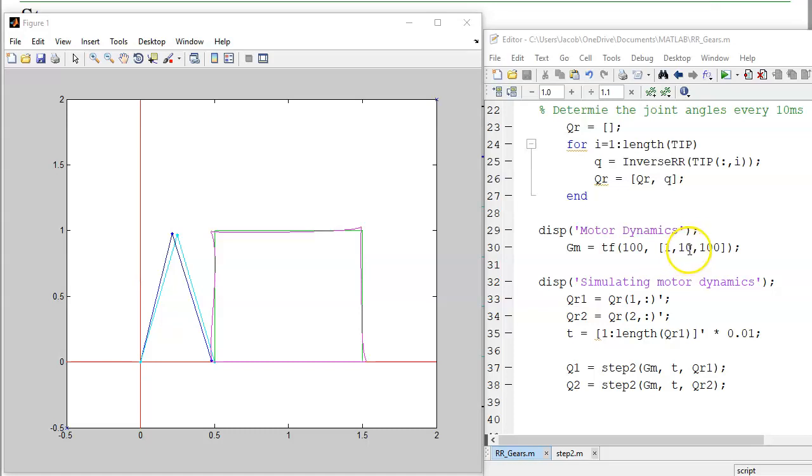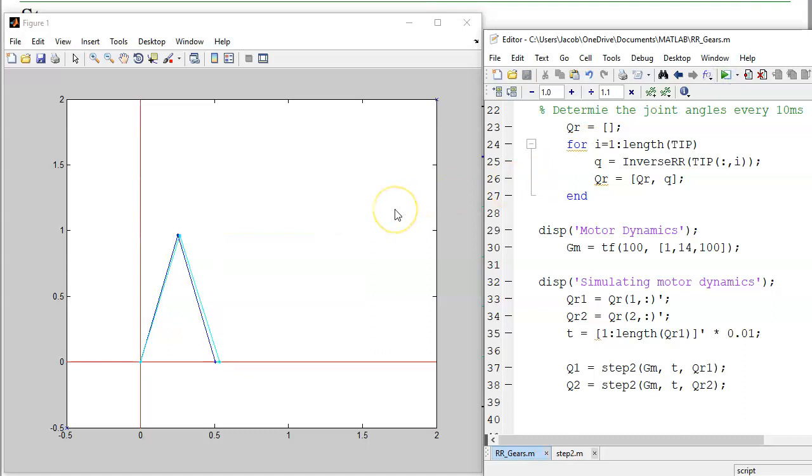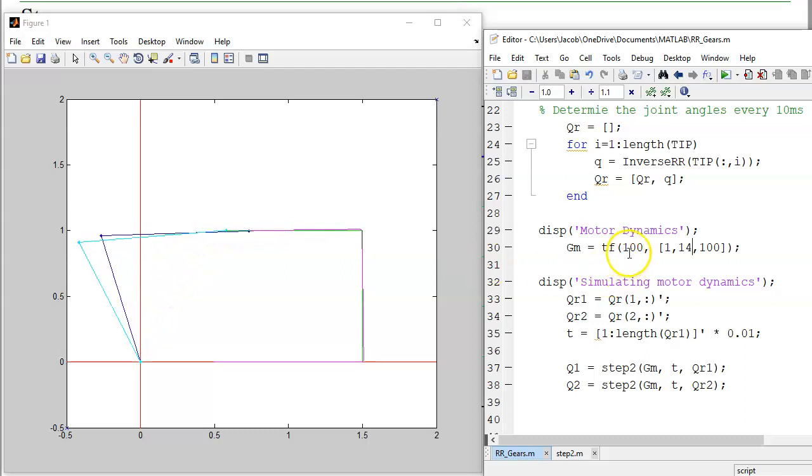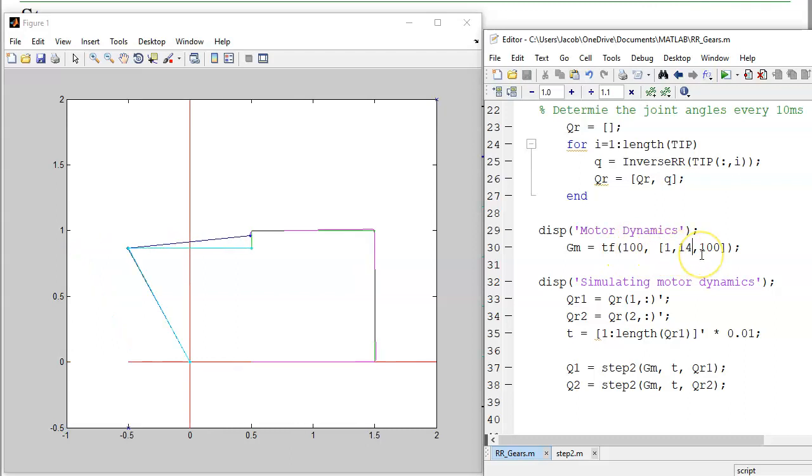In terms of the simulation, that'd be just changing this middle term right here with PD feedback. If I take this, this has roots at s squared, amplitude is 10 and 45 degrees. This has poles at -7 plus minus j7. What that does is a little more friction actually speeds you up a little bit. And now you see the actual angle, the dark blue line, is following the desired angle a little bit better, less oscillations. But it's still lagging. The problem again is the numerator polynomial doesn't match the denominator.